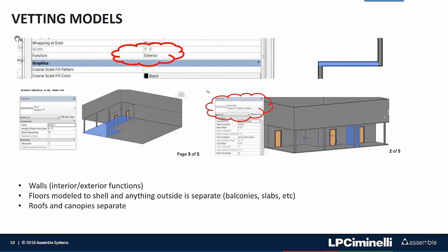Also, a lot of the buildings that we build, there's exterior balconies, exterior canopies, outdoor spaces that are suspended or built off the exterior shell of the building. And in a lot of the models, the flooring of that balcony will also be the same flooring as the slab on deck for the interior of the building. And those two examples are estimated separately. The estimator would look for a square footage and volume for the balcony and a separate square footage and volume for the interior space. The interior space represents the overall BGSF of that floor, whereas the balcony represents a different quantity.